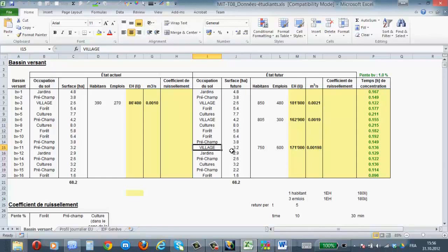we are not going to design a very big structure, because if we design a big structure, then the velocity will be less than the minimum required. The minimum required velocity in a sewer, especially in combined sewers, is 0.7 or something like that. And most of the time 1 meter per second is good, as it is a cleansing velocity. You see, it will clean by itself. So minimum velocity always has to be considered in the design process.